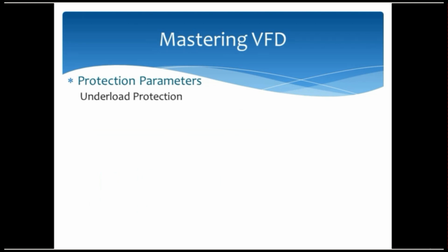In contrast to overload protection, there is underload protection, which means that the motor will trip as underload trip. If it is using less current than what it is supposed to be, it will display underload trip. However, it is important to know why we need this feature. We will explore this question by an example.